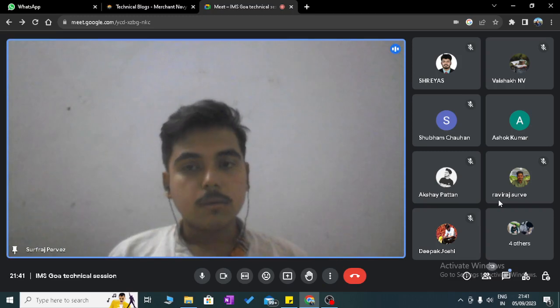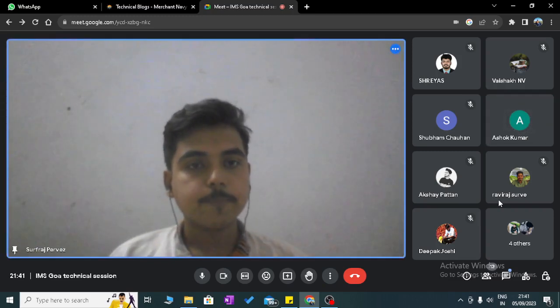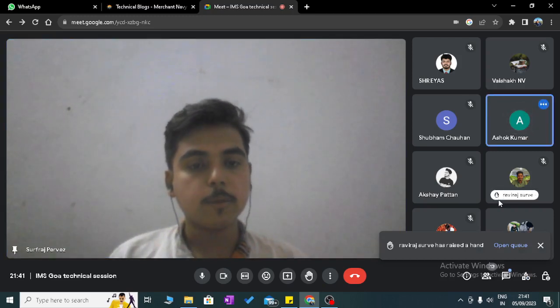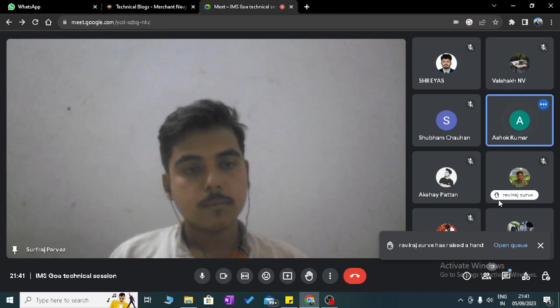Okay. Your answer was correct. You can add one or two more points. Yes, Ashok, please. Cavitation occurs when liquid turns into vapor at a low pressure. It occurs due to insufficient net positive suction head.